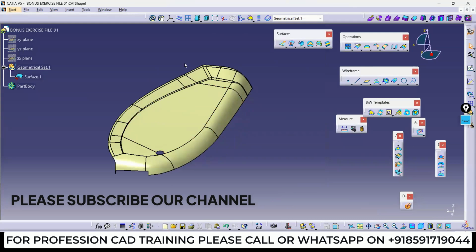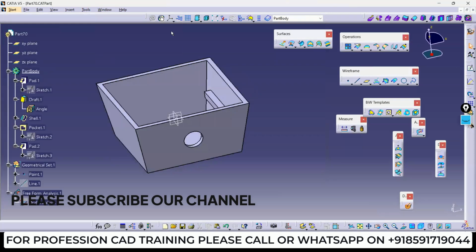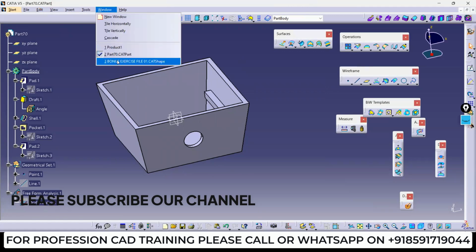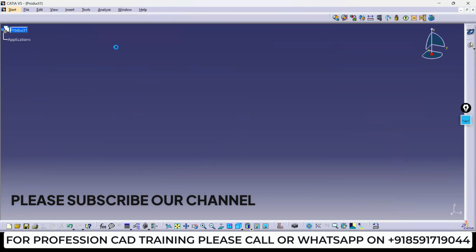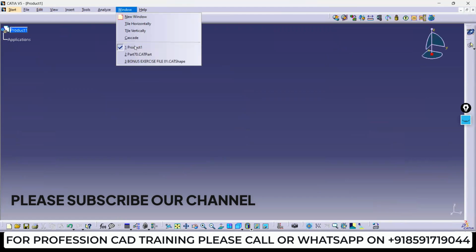Specifically, if you see, this is a surface part, so the extension is CATShape. As per the file, the extension will change. If you go to the part, now the extension is CATPart. This is for solid, you can see CATPart. For CATShape, this is a surface part. If you go to the product, it will create a CATProduct. In detail, we'll see in the next few sessions.